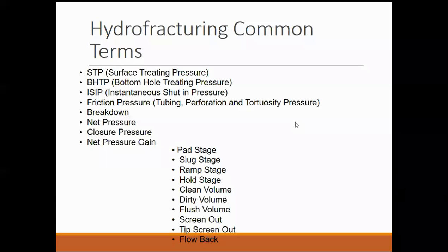What is the screen out? If you're not able to pump the job, and in between a sand stage your entire wellbore is filled with sand, and you're not able to pump anymore into the formation, that situation is called a screen out. So these are to be avoided because they will require a lot of time, because you will have to clean the sand as the entire wellbore will be filled with sand. So just to reattempt your job or go for the next job, it will require cleaning out of that sand first. So all these things are to be avoided.